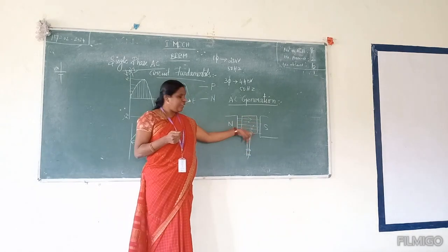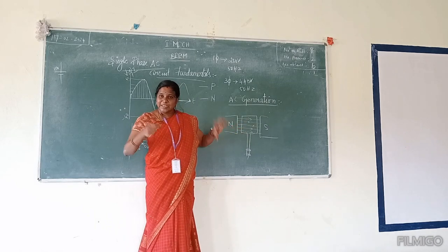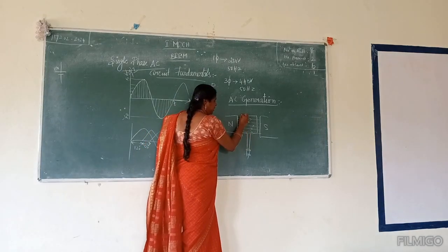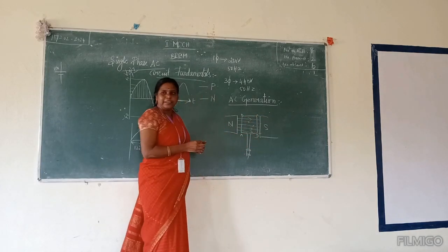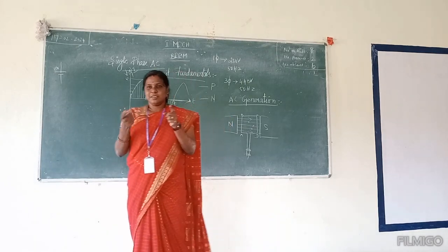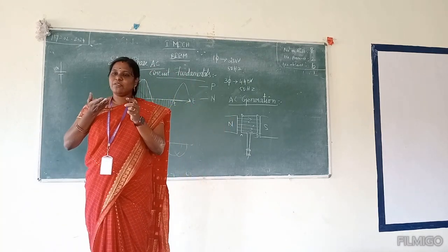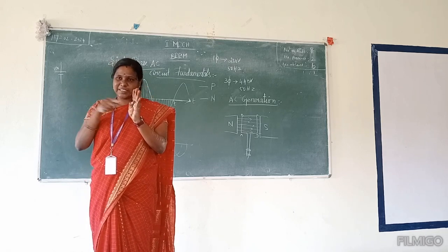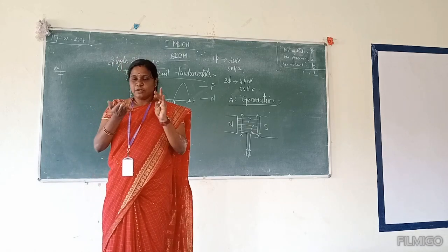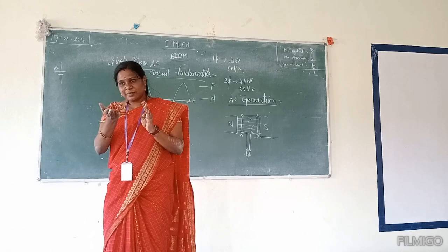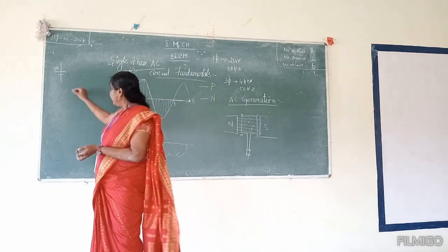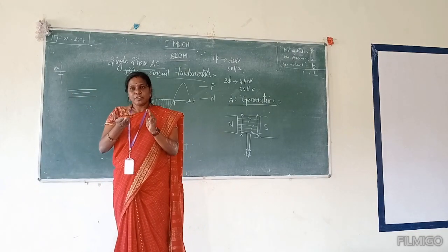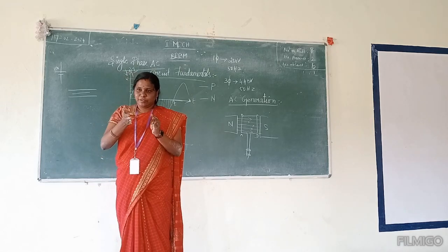Okay, just for simplicity, we are having one coil. In real time, there will be many coils. They will rotate the conductor. Say for example, we have A, B, C corners of the conductor. The conductor will rotate. Imagine this is your flux lines, and you have a coil here. The flux lines are parallel. These are the magnets. The coil will be placed at the middle of the flux lines, inserted like this, parallel. So nothing will happen. Now we rotate the coil.